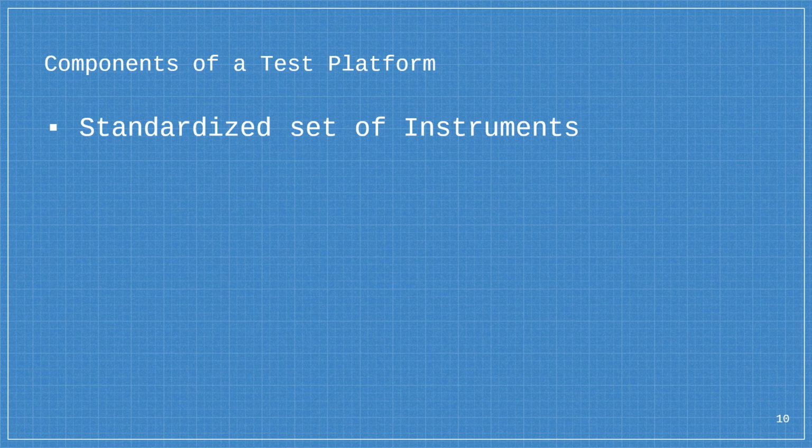And this goes as a specific, for instance, if you're putting a DMM in a PXI crate and you put a DMM in slot 2 of your tester, you always put it in slot 2 of a tester. If you filled a tester variant that doesn't need a DMM, slot 2 is empty. You don't fill it with another card.